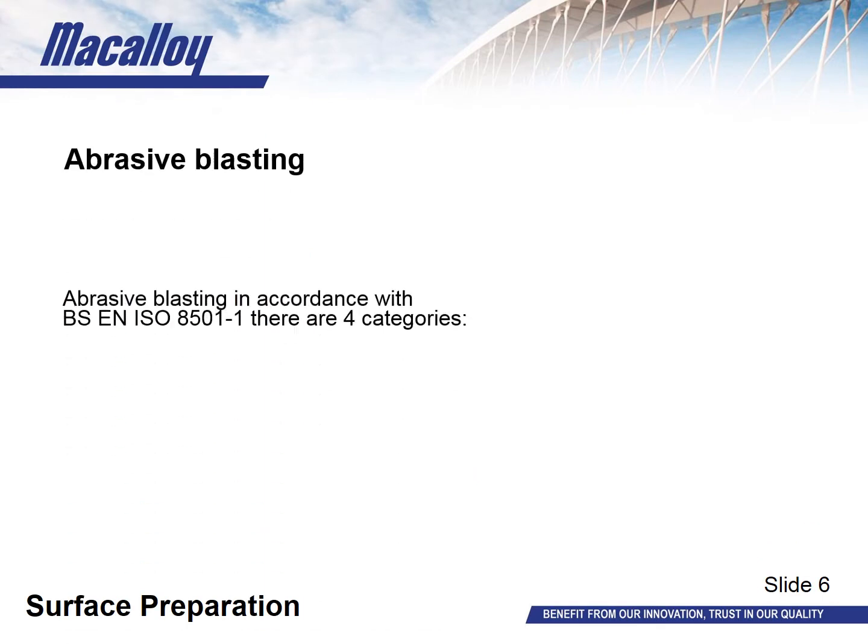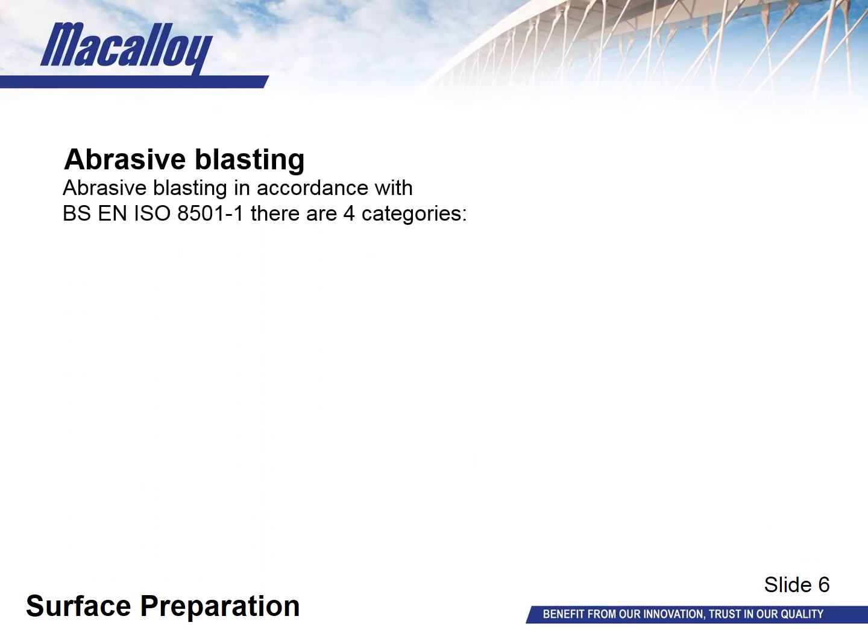Prior to any coating, the steel must be cleaned and prepared. At Macalloy, we generally opt for abrasive blasting. This is done externally in accordance with EN ISO 8501 Part 1, which outlines the 4 categories below.